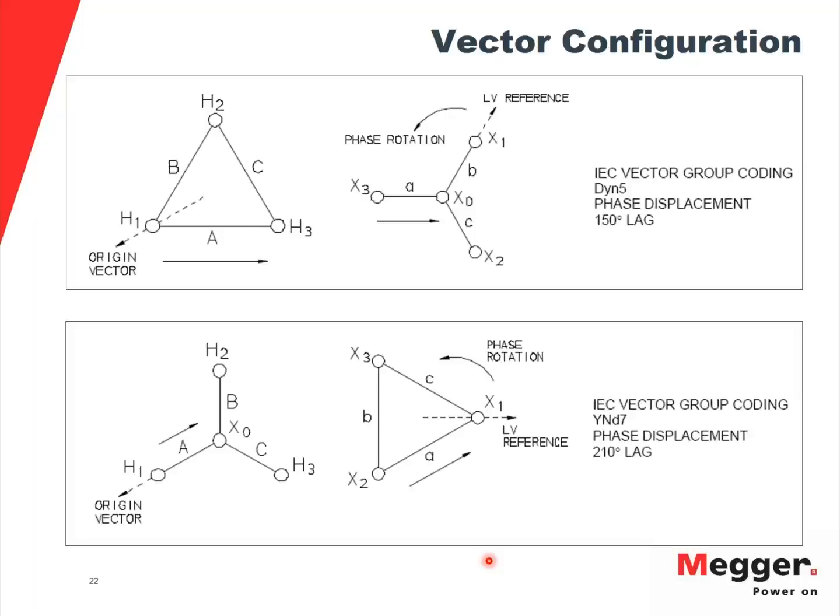If you look at the way the test set is fixed for this test, you will typically do phase A, or whatever coil you have selected, and you go one direction with your tap changer, and then you go from the last position to the first position on the next phase, and then you go again forward or backward on the last phase. So it is better to see, and you can compare what is the response on each of the tap positions. So yes.